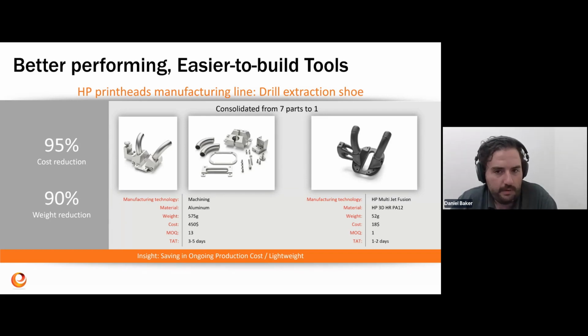Looking at that same part on the right, they were able to reduce the cost about 95%, going from a machined aluminum to a printed plastic, while achieving the same function. This is a low volume, low impact part, but a drastic savings just by changing your mentality. The part has always been CNC'd. Why not 3D print it? It doesn't need to be aluminum. Nylon 12 is a suitable material. And then you ultimately end up with a better, more efficient part.